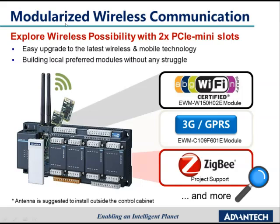Modularized wireless communication is one of the core design concepts of Advantech 3600. On the front panel of Advantech 3600, there is a white plastic cover. Behind this white plastic cover, there are 2 mini PCIe slots for the wireless communication, and the 2 mini PCIe slots are 1 half-size mini PCIe and 1 full-size mini PCIe. The customer could use up to 2 types of different wireless communication interfaces at the same time in the application, and it has the Wi-Fi, 3G GPRS, Zigbee module to choose from.